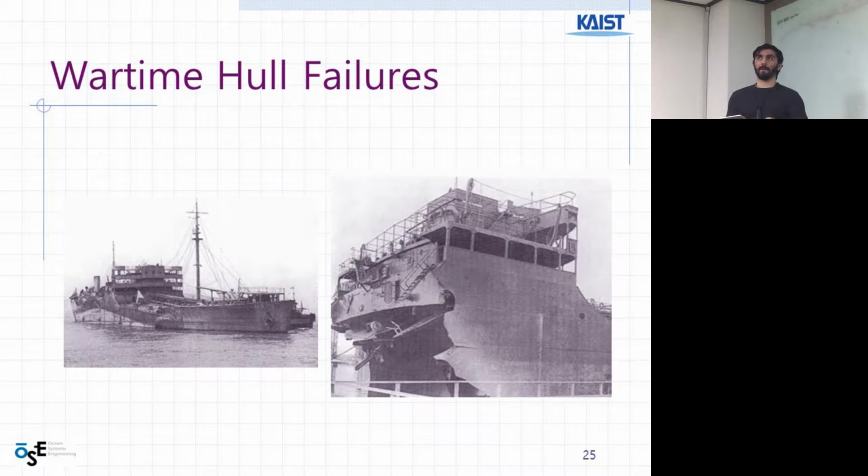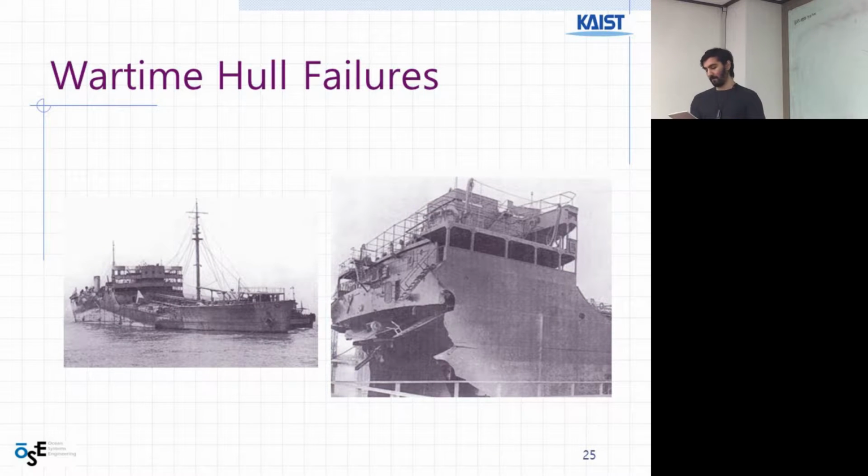A common warning for a possible hull breach can be an unusual collection of water on the deck and a slowing of the rolling period of the vessel. Hull failure can be due to corrosion or fracture, which itself can be due to collision, overload, contact, or grounding.